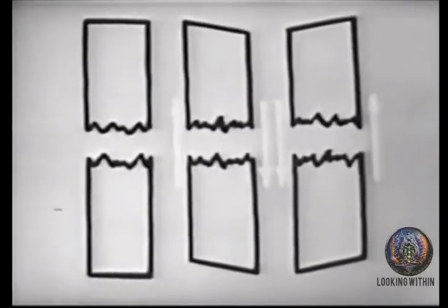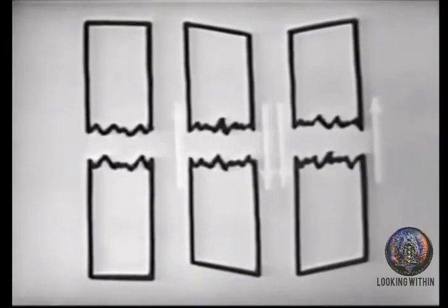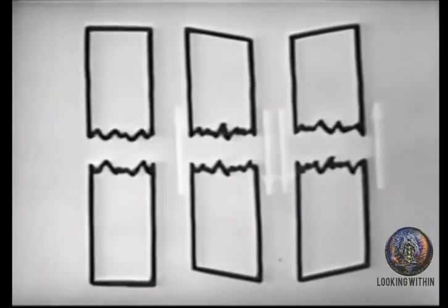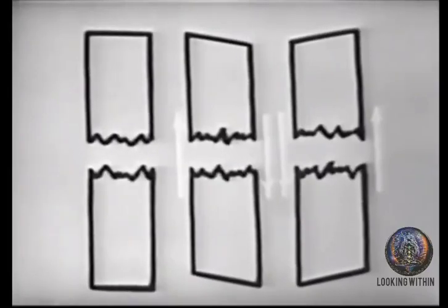You might ask, how is this accomplished? Simply by increasing the feedback to the point where the crystal is shocked into vibrations at the odd harmonic rather than the fundamental frequency. And let's determine what's happening when this is true.